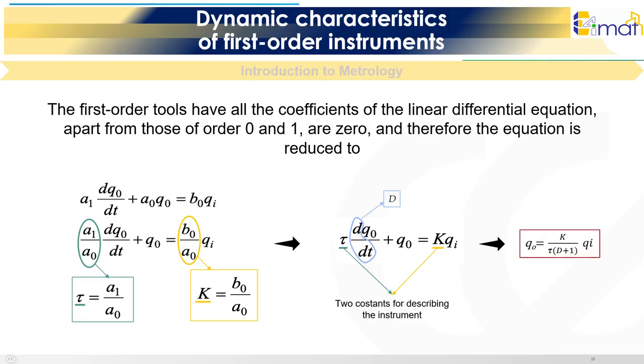First-order systems include instruments whose differential equation contains terms up to the first order. A common example is the bulb thermometer, where the thermal expansion of fluid in the capillary determines the output. The response depends on the time constant, which describes how quickly the instrument reacts to temperature changes. Mechanical delays due to fluid inertia are typically neglected for simplicity.